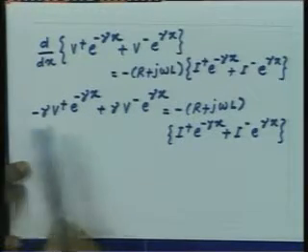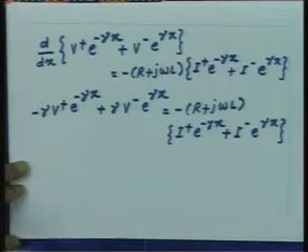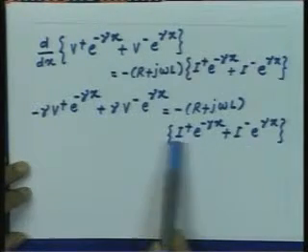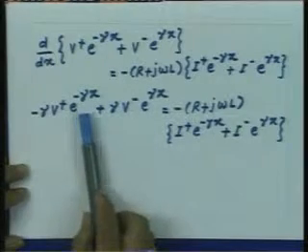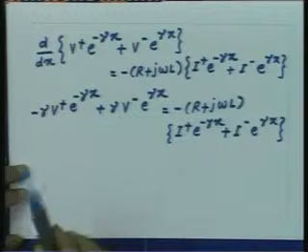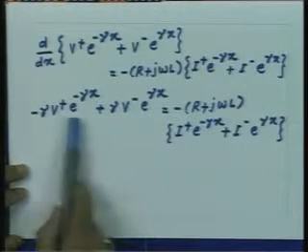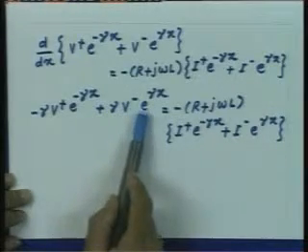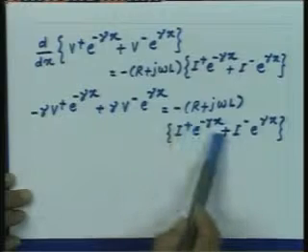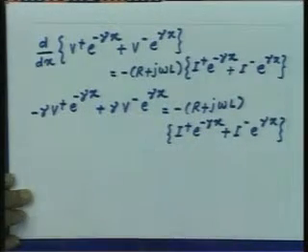At first look, it appears that there is one equation which is relating the voltages and currents. However, if you look at it a little deeper, you will notice that these two terms, the V plus and V minus terms, are representing two waves which are travelling in different directions. Similarly, I plus and I minus terms are also representing the current waves which are travelling in two different directions. This relation, which is the general relation between the voltage and current, has to be satisfied at every location on the transmission line. Since the two waves which are travelling in opposite directions have different phase histories, you cannot satisfy this equation for every value of x unless these individual waves satisfy the conditions at every point on the transmission line.